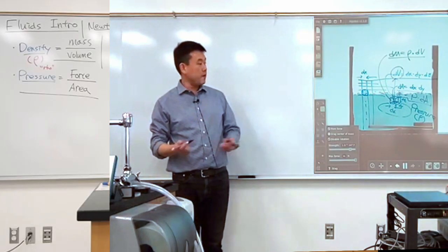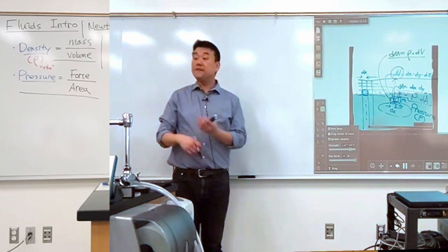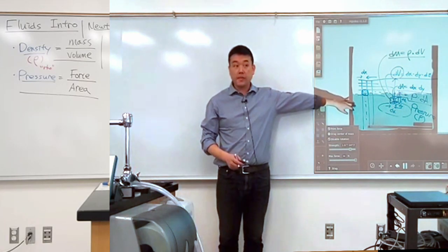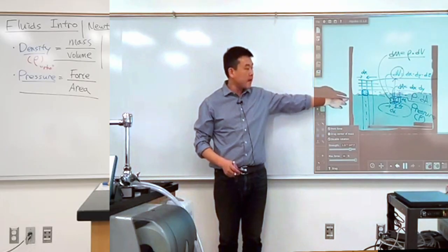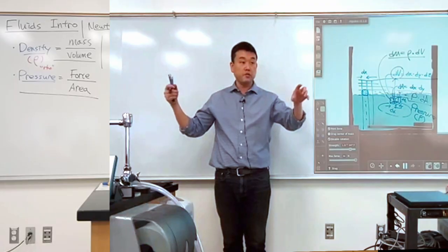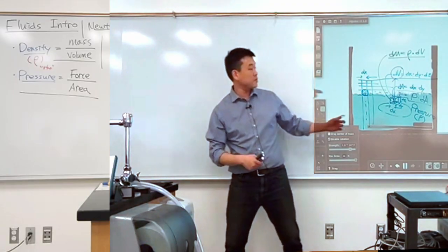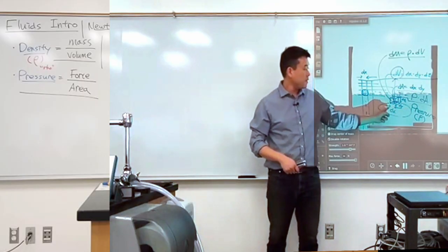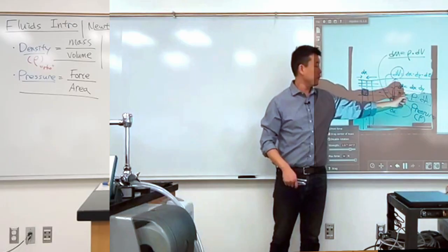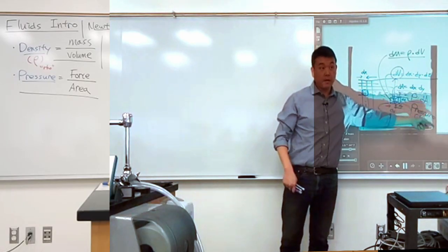So this is how we describe the infinitesimal aspects of fluid, so that at any given time we can imagine taking the fluid, breaking it up into smaller pieces that we need to analyze, and then if we know the pressure, for each one of these elements we can describe the amount of force on it by taking the pressure and multiplying it by area.